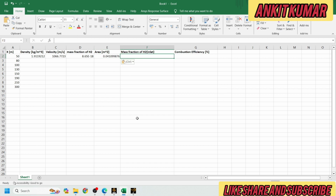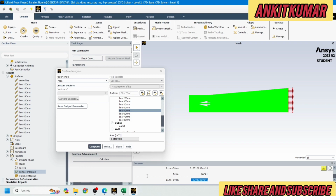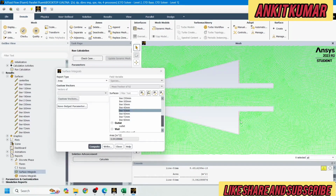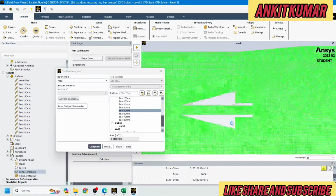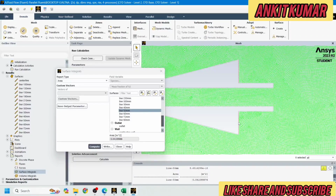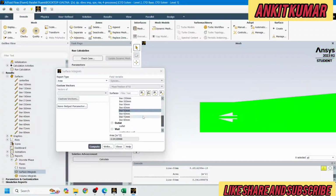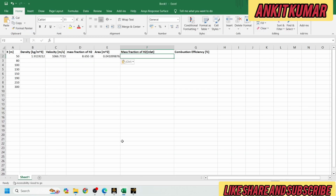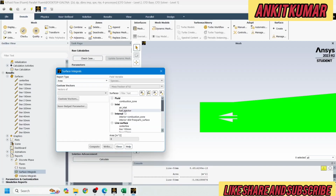Again go to mass fraction of hydrogen at the inlet. Since this phase and this phase are our inlet phase, in order to calculate the inlet value from this edge, we can directly select the fuel inlet part here, deselect this one, remove the selected line 50 mm, and click on fuel inlet. It is asking for mass fraction of hydrogen at inlet. Hydrogen at inlet means how much mass fraction is coming out from the fuel injector, that we will calculate. So select this one, fuel injector.